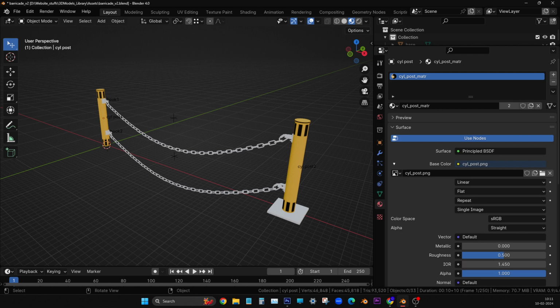Generally in Blender, the light is always dim. We have to give more intensity to it. So you see how many watts it is. Come to the right side of the panel. There's a properties panel below the outliner.